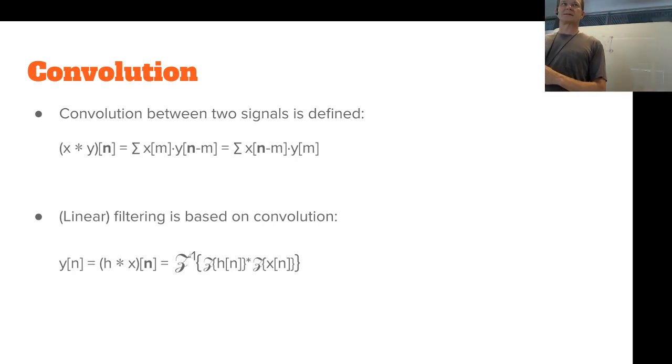It actually does, since this is the convolution, which is equal to frequency space multiplication. So what is your filter doing? What does a filter do to the signal? Analog filter. Yeah, you measured this low pass filter, the amplitude responses, right? And then tested everything and something like that. But anyways, the convolution is roughly the same as multiplying the signal with the amplitude response. So basically, it's a filtering operation.